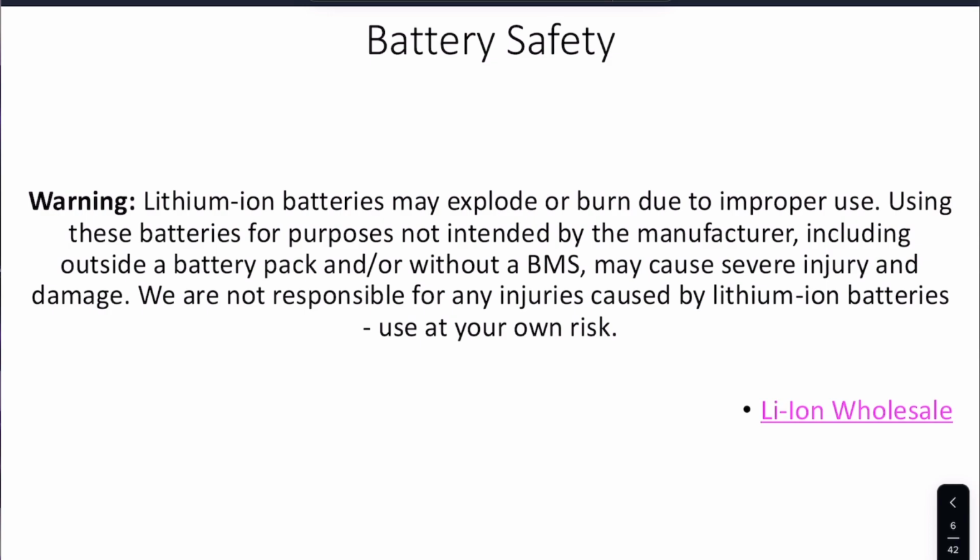That brief little tutorial on circuit theory is really just so I can use some of that terminology when talking about our safety requirements and the specifications of the components that we'll actually be using this week. So I'll start with this warning on battery safety. Lithium-ion batteries may explode or burn due to improper use. So if you drop them and you notice them bulging or some damage to them, make sure you let me know. If your battery smells odd or is hot, those are also things you should let me know.